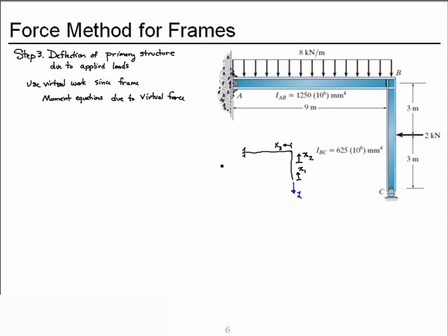And so let's start with a free body diagram of the frame cut in the range of x1, and let's keep the bottom piece. So it is x1 long. We have our virtual force applied. We have our unknown shear, which is a function of x1. We have our unknown virtual moment, which is a function of x1. Let's apply moment equilibrium.